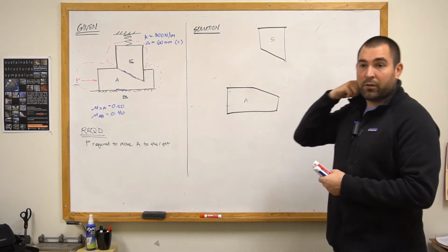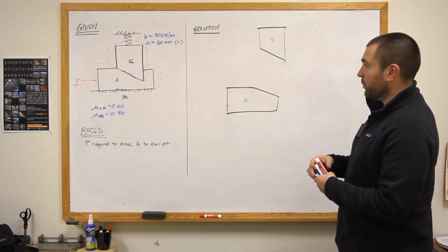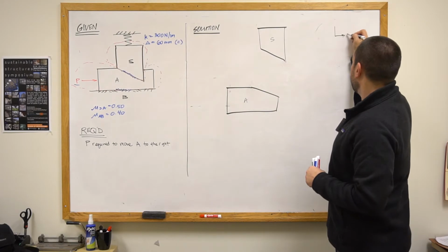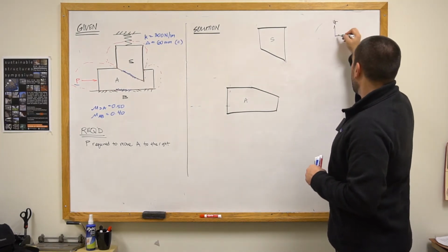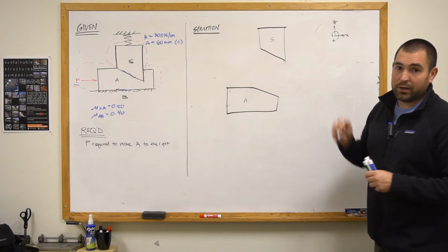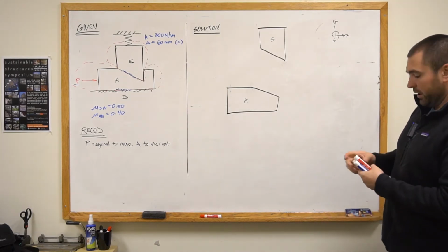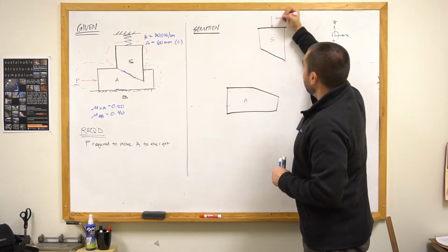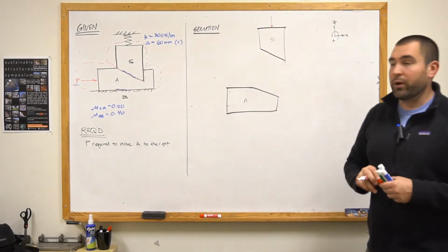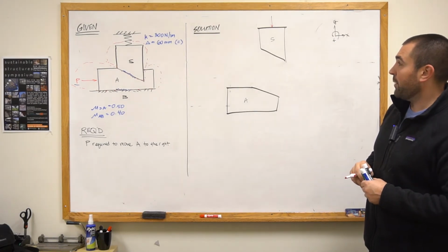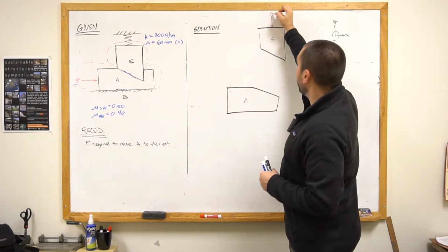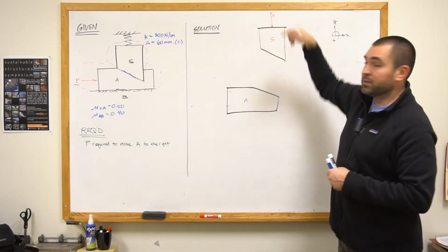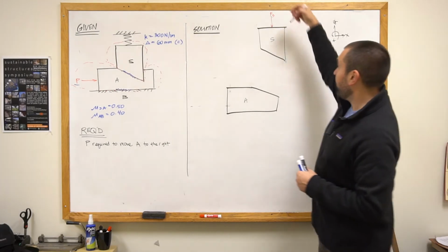I need to look at all of the forces acting on each of these surfaces, and we'll start from the top and go to the bottom. I'll use a consistent coordinate system, our standard X positive to the right, Y positive going upwards. I'm going to have a force acting down on the stub due to the compressed spring at the top of S. Because the spring is compressed, it's going to be pushing against any surface it is connected to, and that's why I point it downwards.